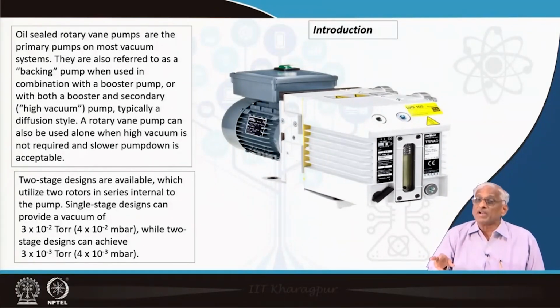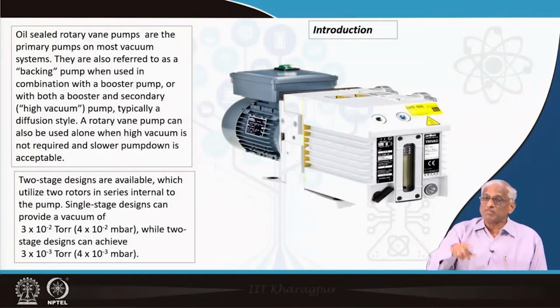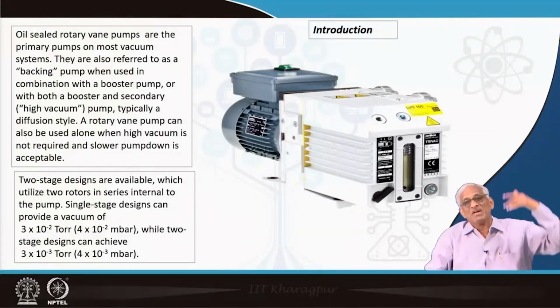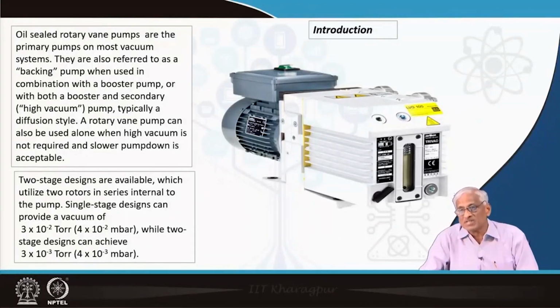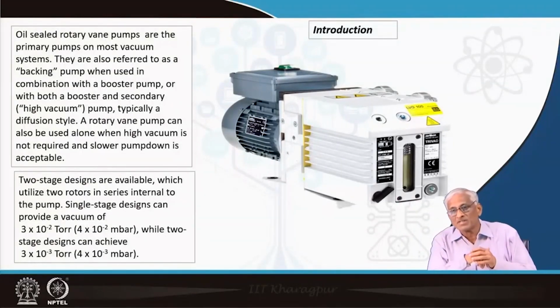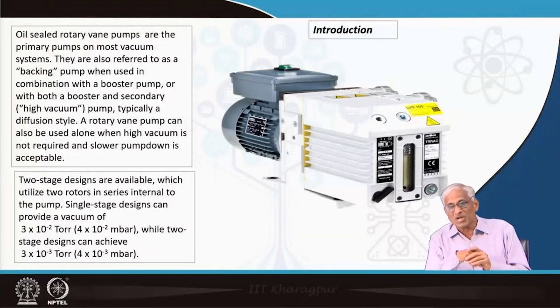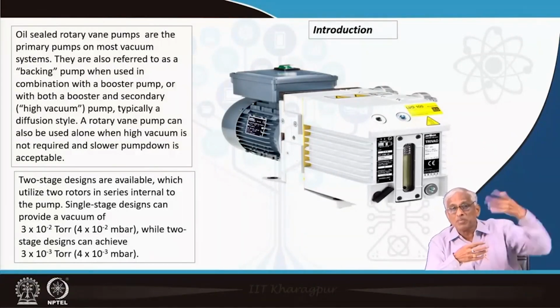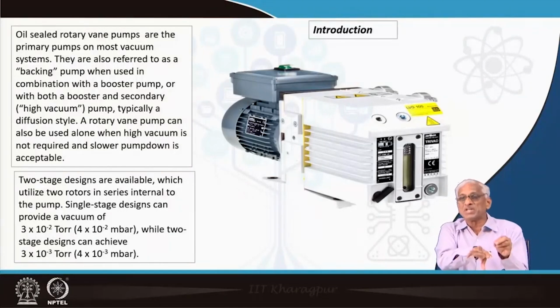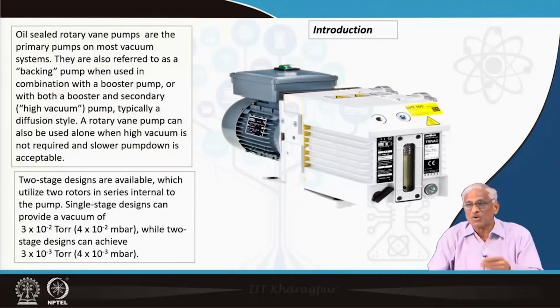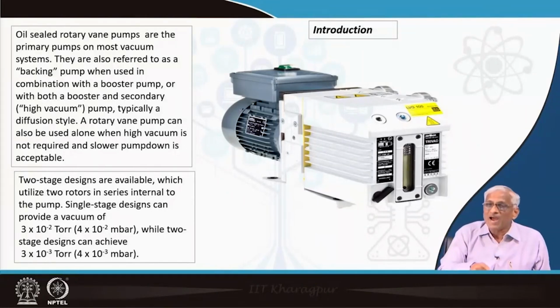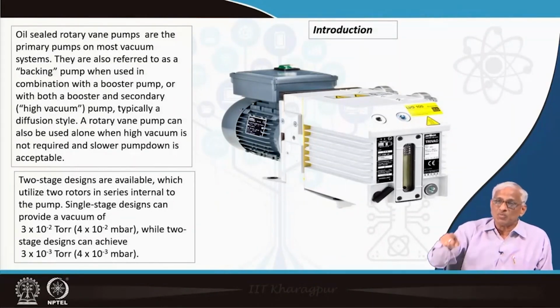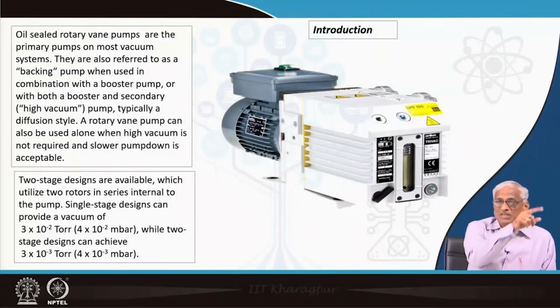It can also take help of another pump called roots blower, together forming a backing action to a high vacuum pump, depending on loading situations. In very large scale vacuum metallurgical furnaces, the rotary pump has to produce minus 2 torr so that the diffusion pump will take over, but it has to produce very high speed, very fast, and later it has to match the diffusion pump exhaust conditions. So, it requires a boosting of this rotary pump by a booster called roots blower. At that time the roots blower and the rotary pump together, called a booster stage, act like a backing pump.